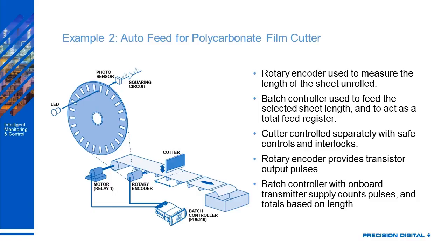it allows the LED to shine through the slots that are in the disk. And as the light from the LED hits the photosensor, it triggers a transistor output, which you can essentially imagine as me flicking a switch closed every time one of those slots passes. So I hit the slot, I close my switch. Once the slot has passed, I open my switch again.